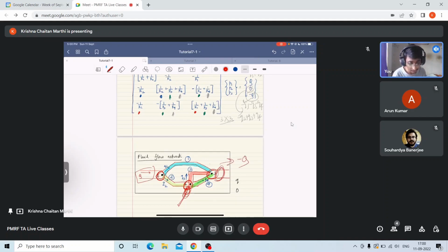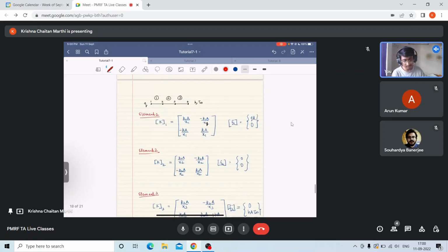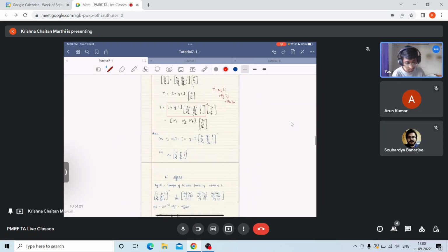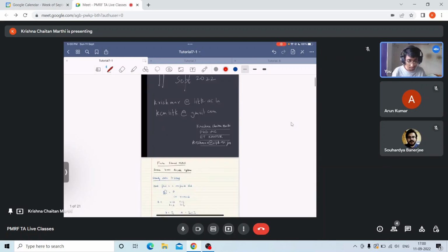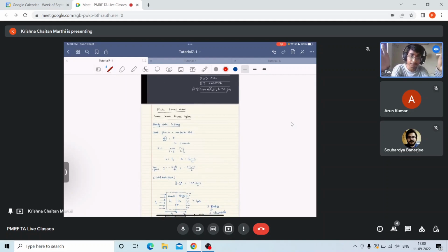So this is just an introduction to finite element. This is not a proper finite element tutorial. This is just how to visualize discrete systems and how to solve them. So we basically consider an element, and in elements we have nodes, and we assume the profiles of elements. For today's tutorial, the elements considered were linear, as the problems we encountered today are steady state problems.